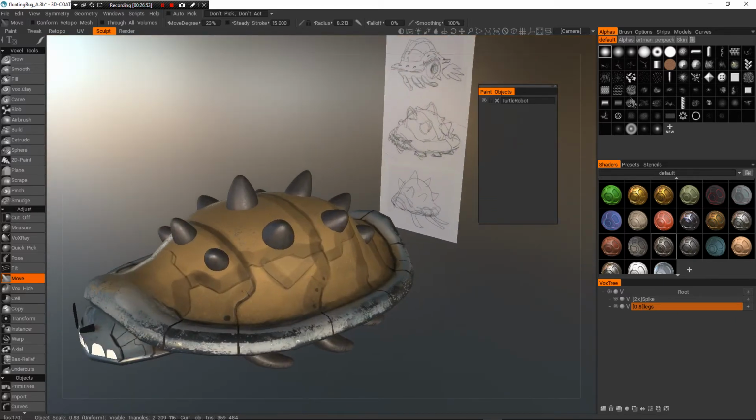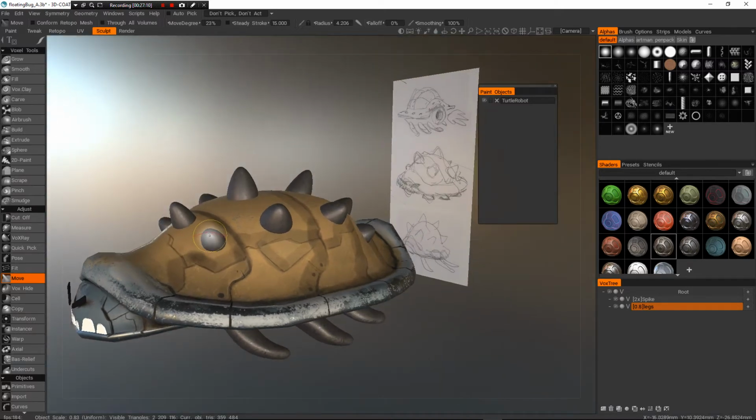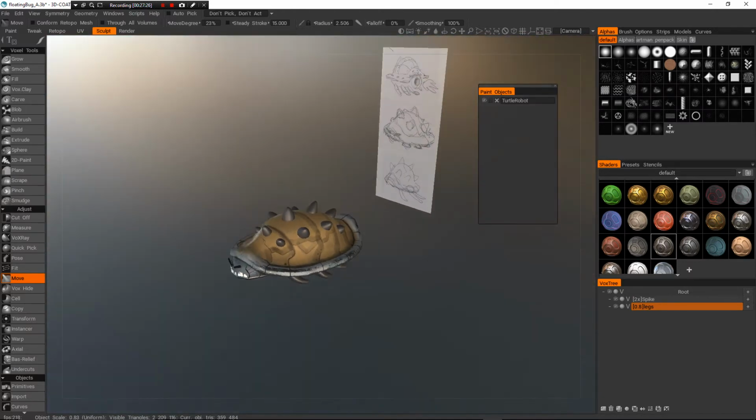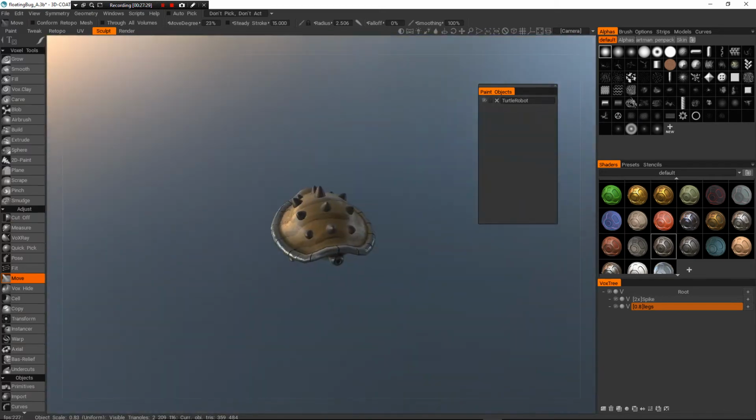Okay, so now you'll notice actually I have 2 million polygons showing. So I've really bumped this up quite a lot. I pressed Control Plus, which I've basically set to be a hotkey, which basically subdivides my entire voxel layer. So I pressed that a few times to bring this layer from about 20,000 triangles to the spikes layer is about 1.8 million triangles. The legs are now about 360,000 triangles. So again, greater density is good for this next step that we're going to take.